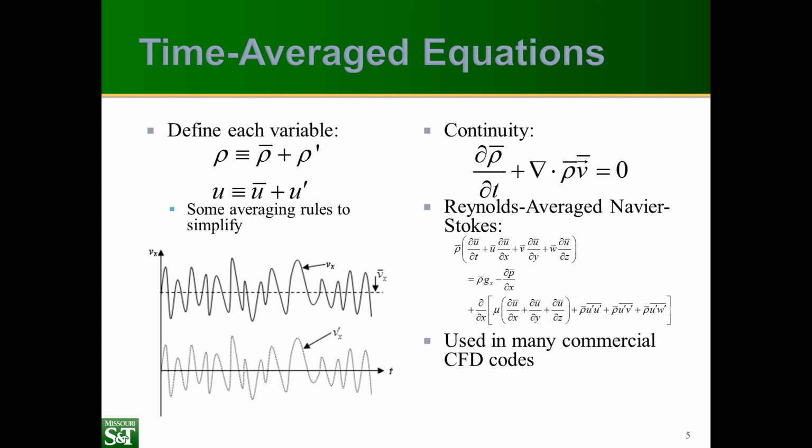The problem is that if we're going to use these equations, we need to develop models for these Reynolds stresses, and that's a pretty complex topic. In fact, there are entire graduate level courses on this topic. So we're going to leave it for later and just acknowledge that if we're going to use the Navier Stokes equations to predict turbulent flows, we need to have some model in place for the effects of turbulence through the Reynolds stresses.